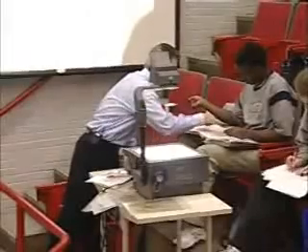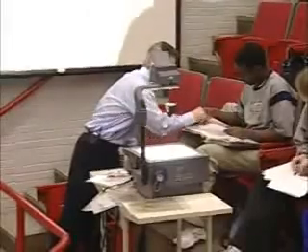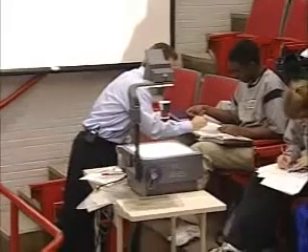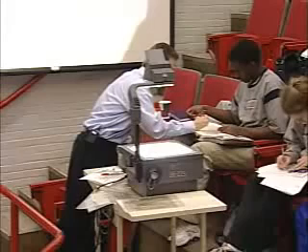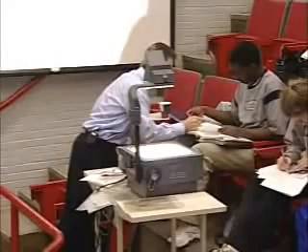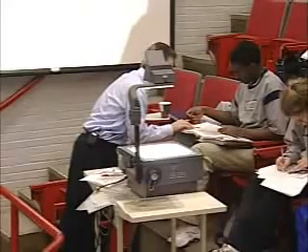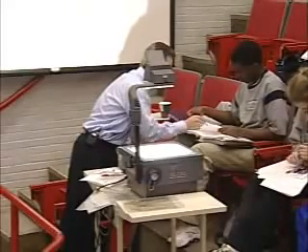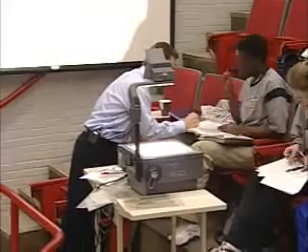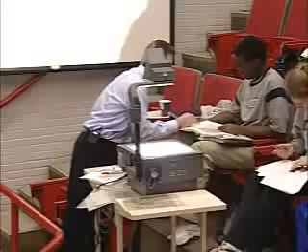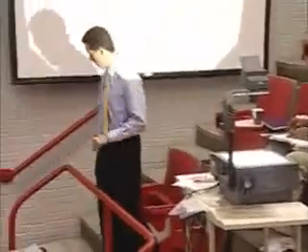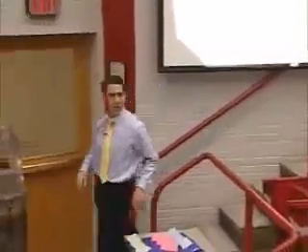Draw it right on top of this so that it's to scale. Yeah, the triangle. So, for example, you could say the flow coming out of this stationary blade row looks like this, right? Because it's got to have this length, and it's got to have this angle. And then subtract off this, that same length. And then this would be sort of the relative frame, 1. So this is what I mean by draw it right on top of it like that, all right?